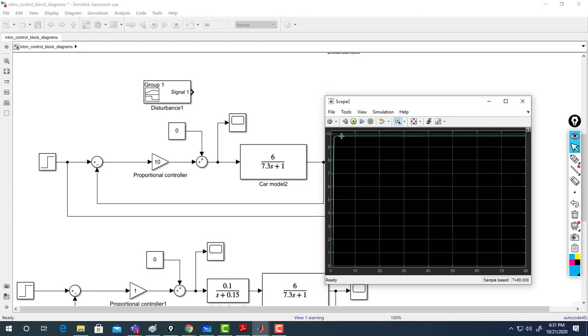But I told you, pay attention. You have a drawback of increasing the proportional gain. So now we are understanding the effect of proportional control. Having a big value of the proportional controller will decrease the steady state error. Very nice. It will make the system faster. Very nice. But pay attention, you have a drawback. One drawback is it will amplify the noise. We just saw in theory that this will amplify the noise.